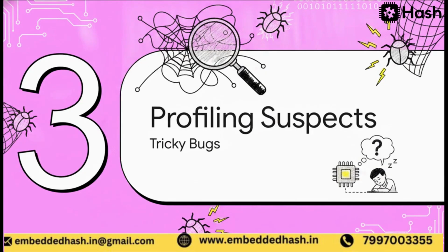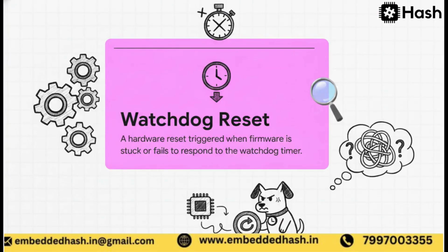Moving on to section 3, let's start profiling the suspects and look at the really tricky bugs that keep engineers awake at night. Our first prime suspect is the infamous watchdog reset. You probably know the drill. If your firmware gets trapped in a loop or deadlocks, it fails to pet the hardware watchdog timer, and boom, you get a hard system reset. It's a vital safety net, sure, but figuring out exactly why the code hung in the milliseconds right before the hammer dropped, that is a massive headache to untangle.